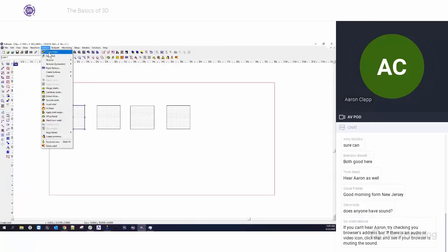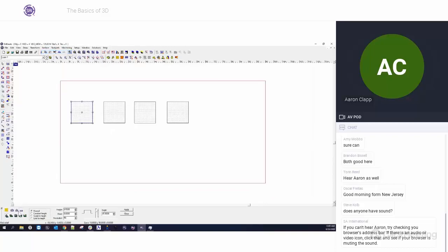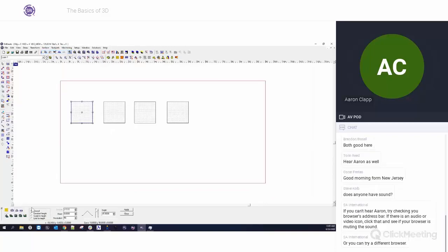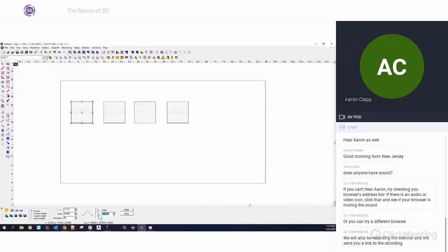So I'm going to say Surface, Create Relief again. This time I'm going to stick with the beveled relief, and I'm going to go through these. So first of all, if we say normal, what it basically does is it grays out the height option for me. And what it does is it takes the size of your object, and then it also takes the angle that you've given it, and it will automatically apply a relief based on those 2 things, the angle that you've given it and the size of your object, when I hit apply.